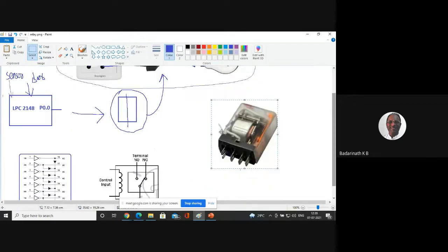In such cases, you can see that this mechanical relay, which is available for 60 rupees, generally works for 2 to 3 years without an issue. Sometimes, if used rarely, it can work for 5 years also. You have seen that some of them are used in water purifiers, and they work for at least 6 to 7 years without any issue. So depending upon the requirement and the frequency of operation, you can always choose this kind of mechanical or electromechanical relay.